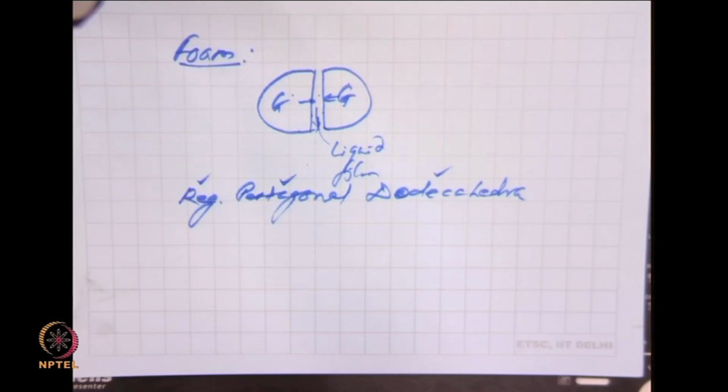Now, if we have this structural idealization that each polyhedral foam bubble is like a dodecahedron, each with 12 pentagonal faces, each face with the same length of side, you have one visualization. You take many such dodecahedrons together. If they are all of same size and you put them together, there is one conceptual catch, that is, you are not able to fill space completely. If you take cubes, you can fill space completely because they will be exactly matching faces, leaving no gap. But in these dodecahedra, there are certain gaps which are not filled. They amount to about 3%. So, it is presumable that those voids are filled up with liquid, forming the films.